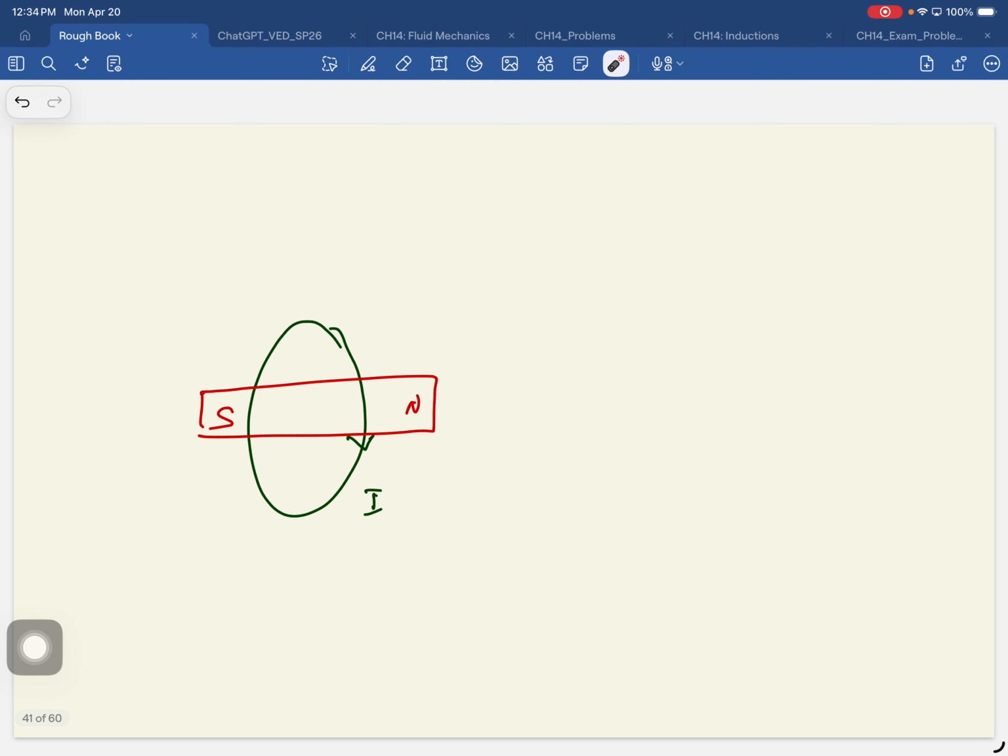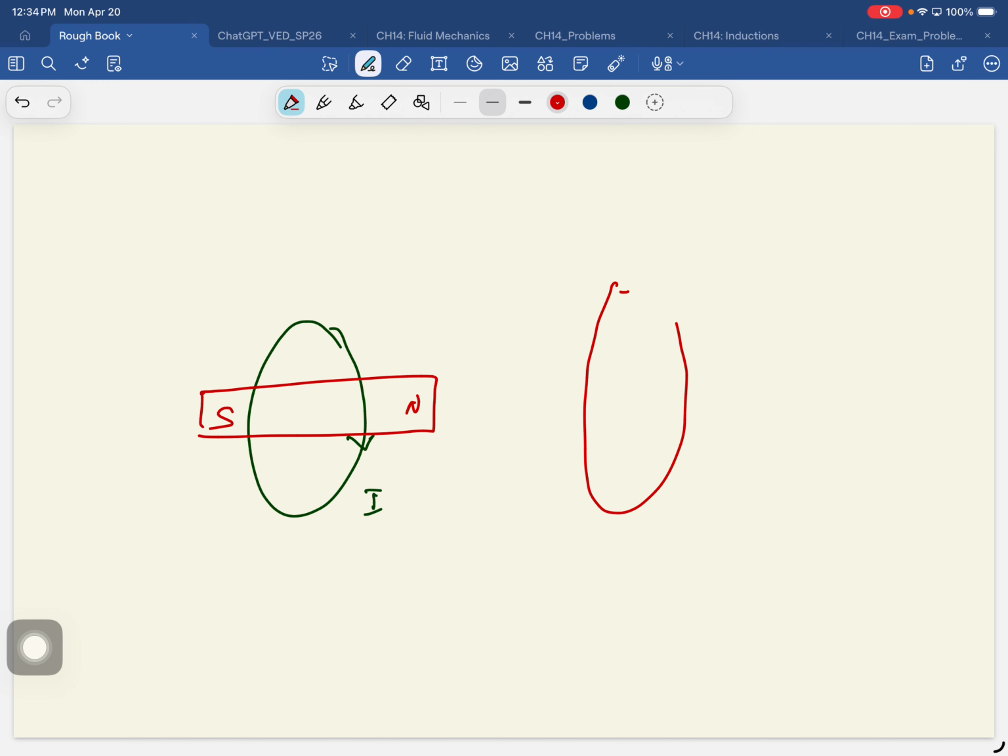Now here's the relationship to Faraday's law. If you increase this current, what will happen? The magnet gets stronger, so this magnetic field increases, and here's a time-varying magnetic field. By changing the current, you've changed the magnetic field. And then if you have another sensing coil like this, the magnetic field through this coil increased, and so that'll induce a current in the sensing coil.